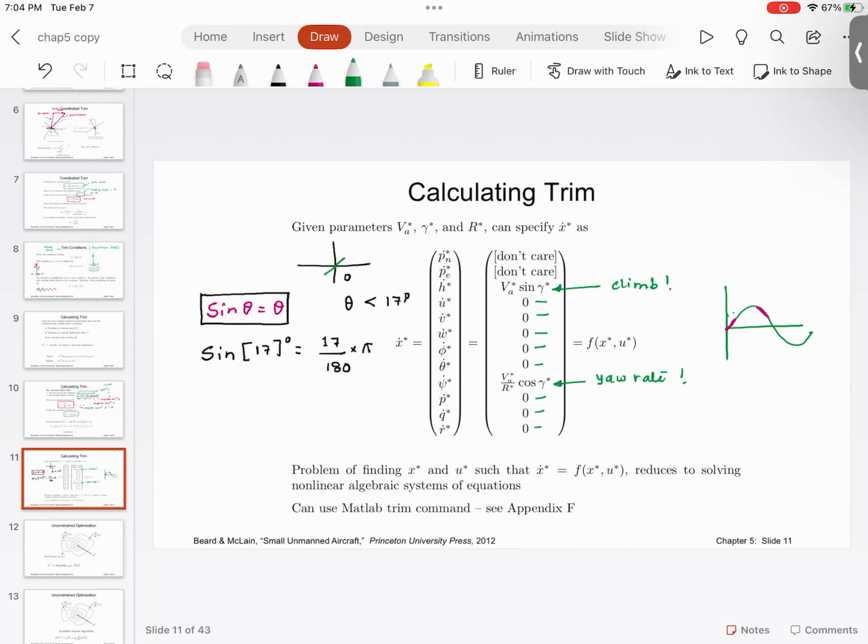Linear systems do. So you find the eigenvalues of the linearized system. If the eigenvalues have negative real part or positive real part, you can confidently say that the nonlinear system is stable or unstable. Yes. But if eigenvalues are positive, wouldn't that mean that pole is on the right hand side? Yeah, so it becomes unstable. What it means is if the linear system is unstable, your nonlinear system is going to be unstable.